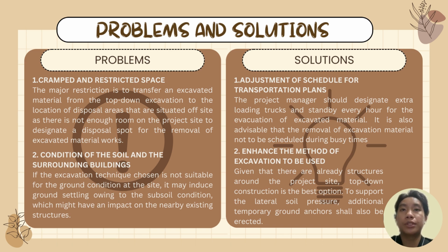Now, the solutions for the problems. Firstly, adjustment of schedule for transportation plans. The project manager should designate extra loading trucks and have them stand by every hour for the evacuation of excavated material. It is advisable that the removal of excavated material not be scheduled during busy times.